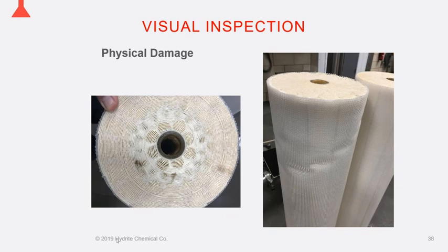It can impact the flow across that element. So you'll end up with dead spots in there where water product will not hit and will not get even flow. So you'll definitely end up with growth in that area where the CIP solution isn't able to get it clean.